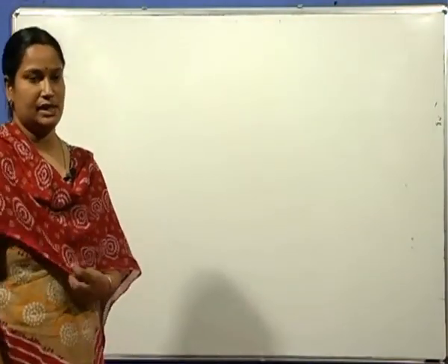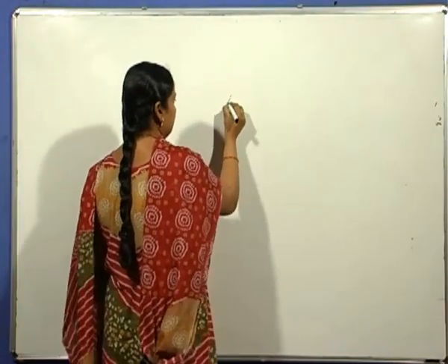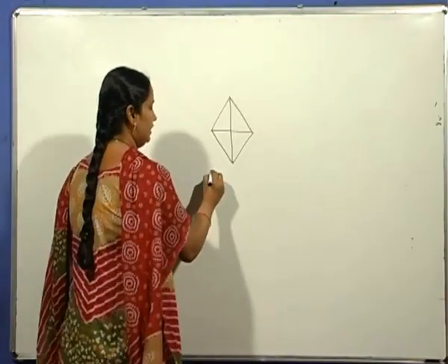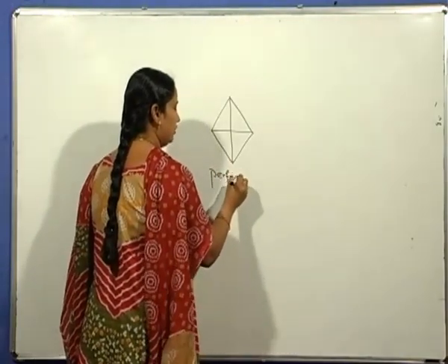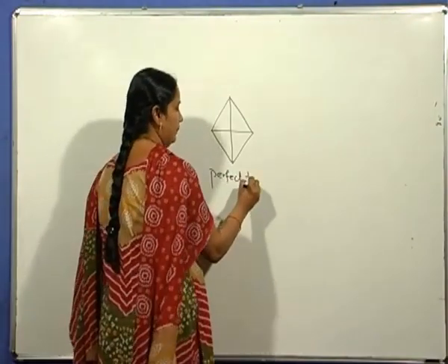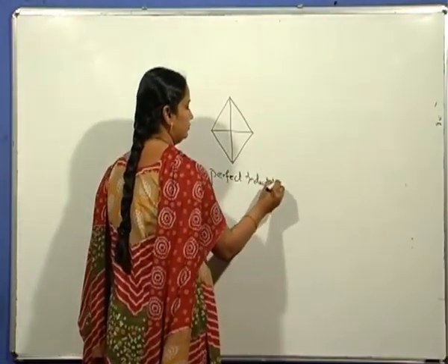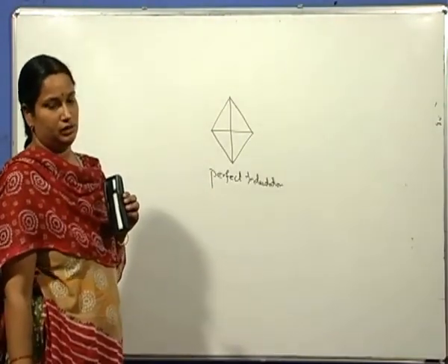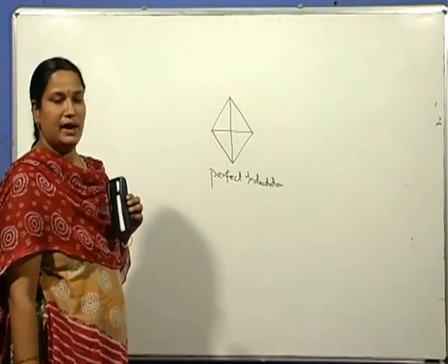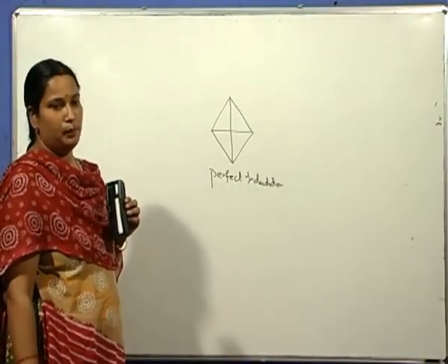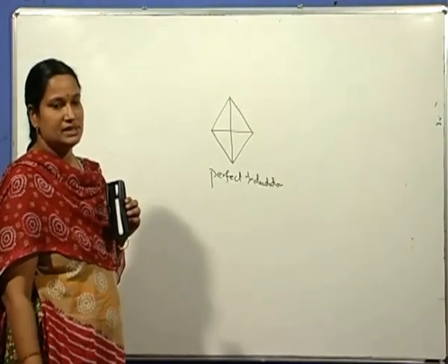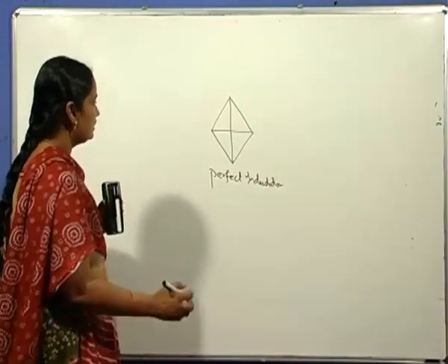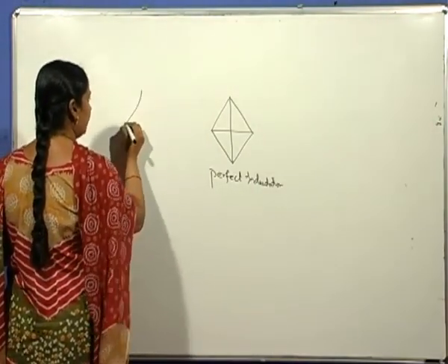In the case of the Vickers hardness test, this is the perfect indentation obtained. Whereas sometimes a pincushion type of indentation or a barrel shaped indentation can be produced, which results in a decrease or increase in surface area.